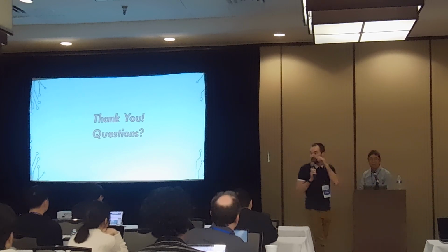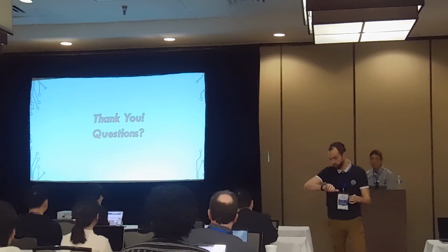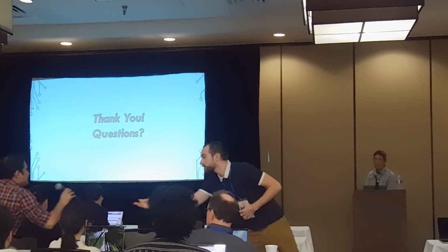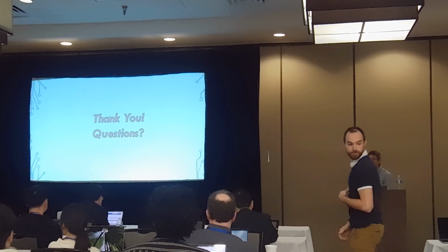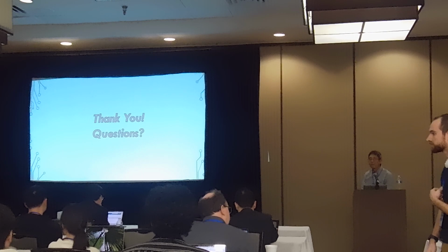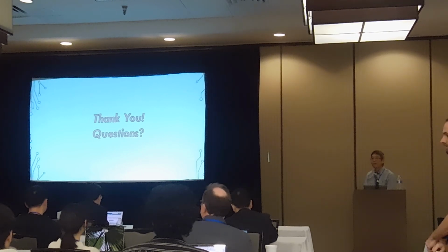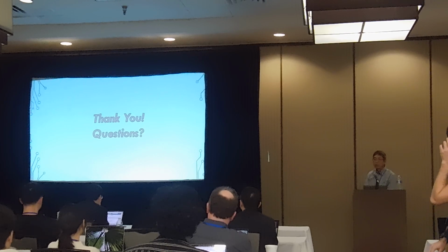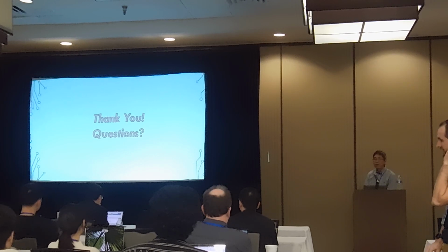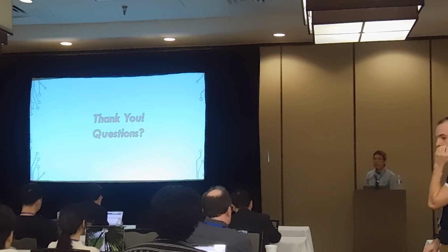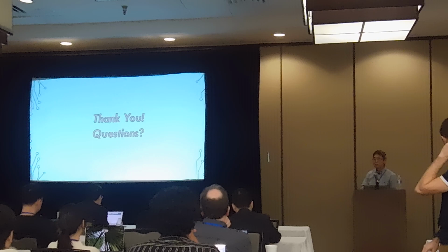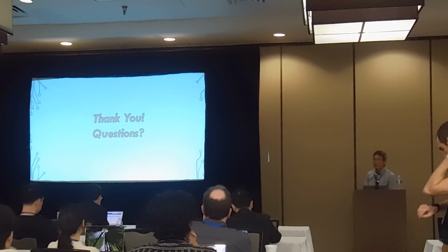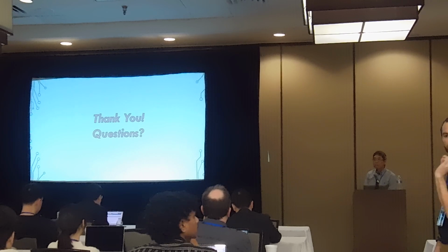All right, anyone else? Dr. Hu talked about two specific implementations of PEs, one in which the PE is a macro, and the other in which the PE is made of standard cells. So for the ASIC part, we have two different works. One assumes the PE is a macro, the other assumes the PEs are standard cells. Do you see any specific differences or benefits of one versus the other?